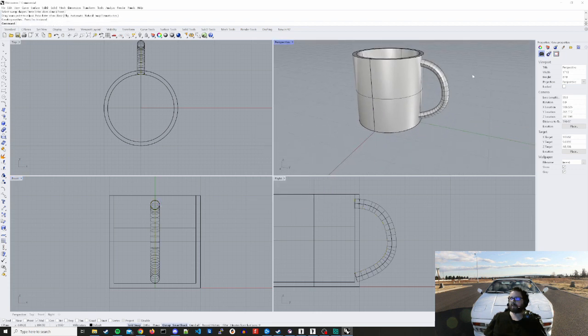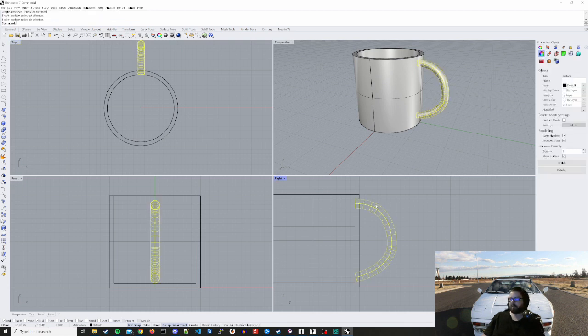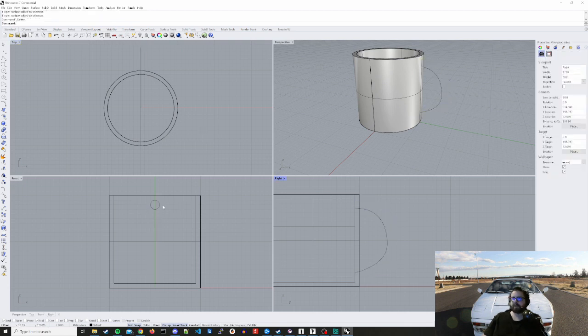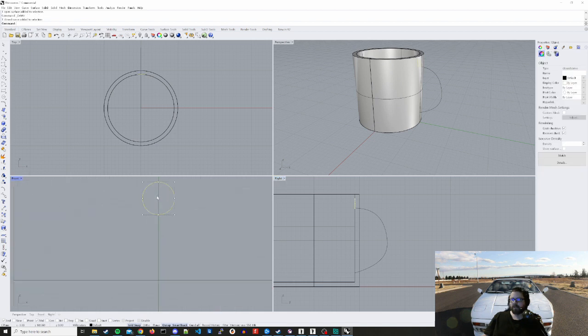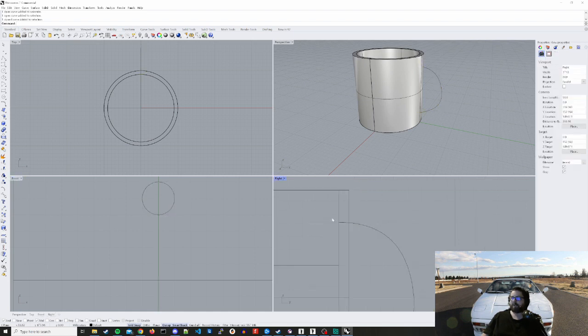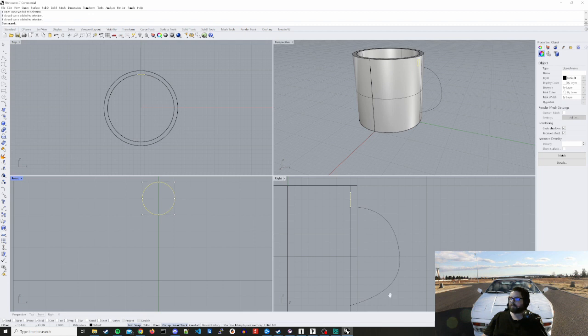It's not the greatest. So what I just did right there, the sweep rail, is you are selecting a shape, the curve that you want that shape to go along. In this case, we chose a circle. So if I delete this and go back, I'll just kind of explain this real fast. The bottom of this circle is at the bottom of this line. They're meeting each other. And when you sweep it, it's going to take and move this all the way down in here and make a surface.